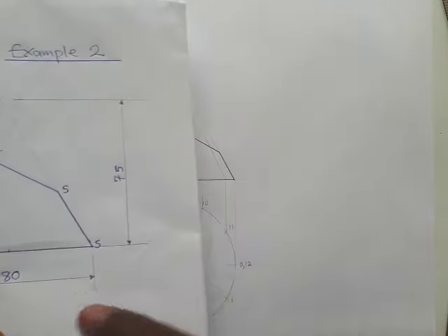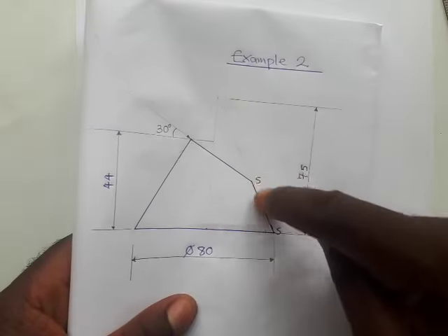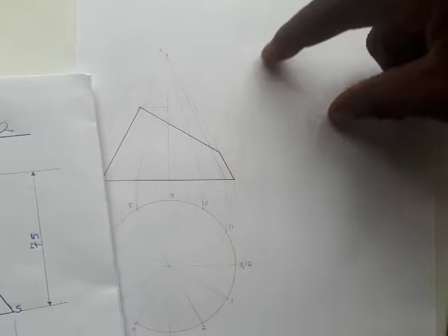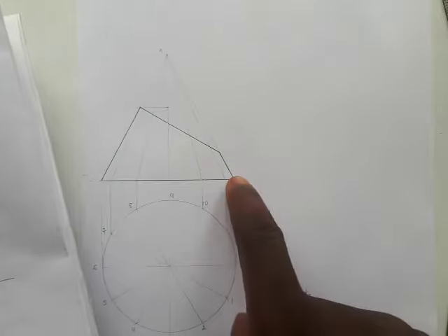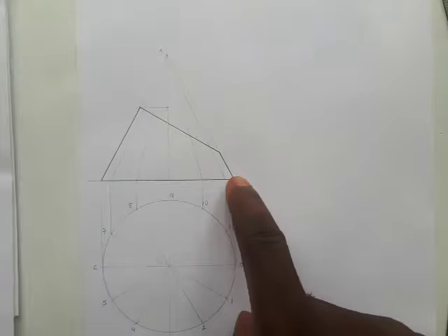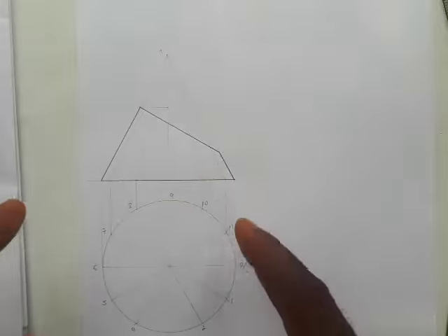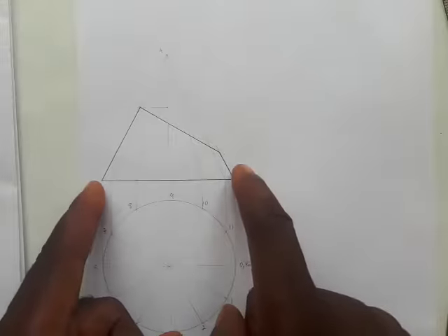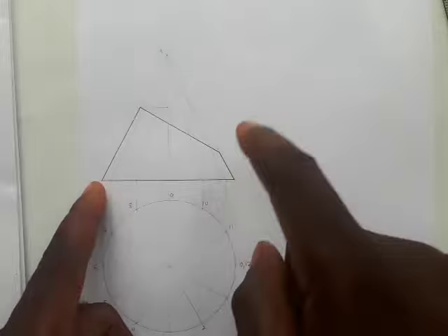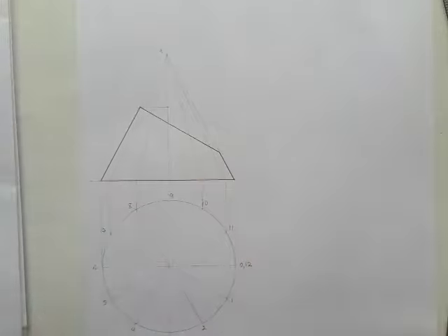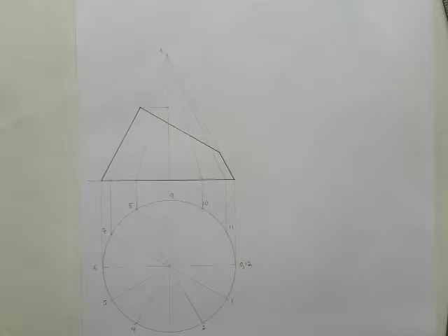Now the next thing is the seam. SS is the seam. These are seams, so that means you have to develop from here. Develop this way. Now this is not a prism. This is a pyramid. Yes, a pyramid, a circular base pyramid called a cone. Now if it were a prism, you would have to apply the parallel line method. But for all pyramids, you apply the radial method. And how do you go about that?